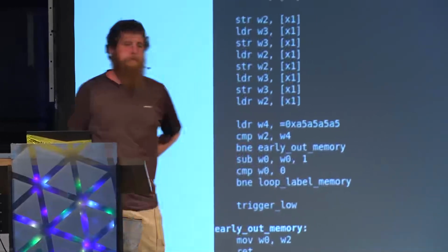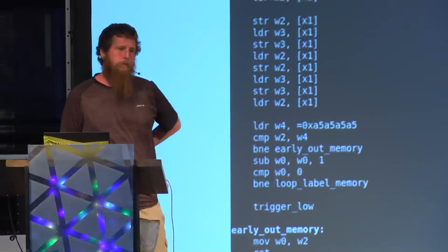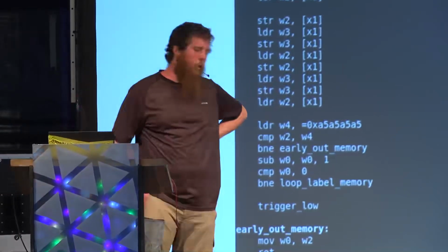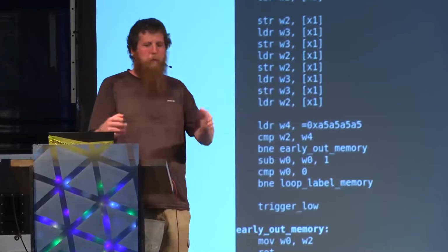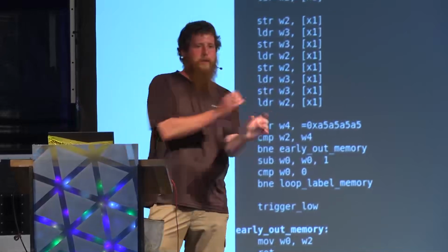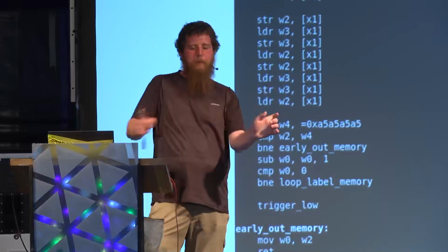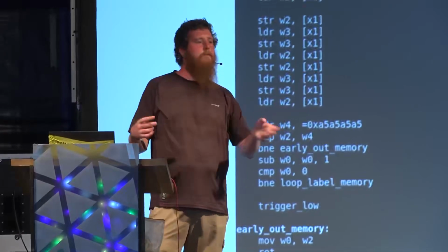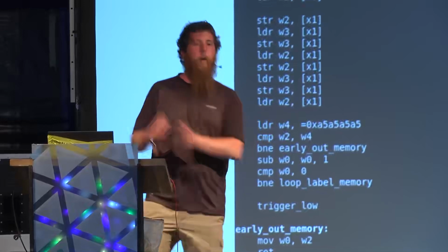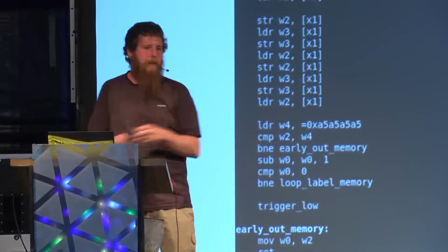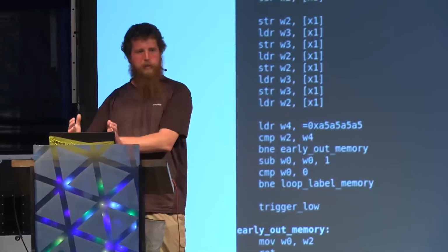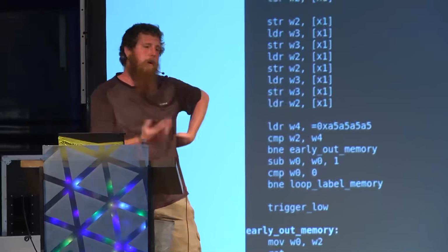And would you also use a trial and error method? Just gather lots of data, like wait. Yeah, exactly, that's one of the many parameters we need to optimize. So we have our trigger, we know when to start, and then we will start randomizing how long we wait before we glitch. And then from there, we'll see, oh, if we wait a long time, we have the desired effect. If we wait a short time, we don't. So we know that we want to optimize towards the longer wait times.